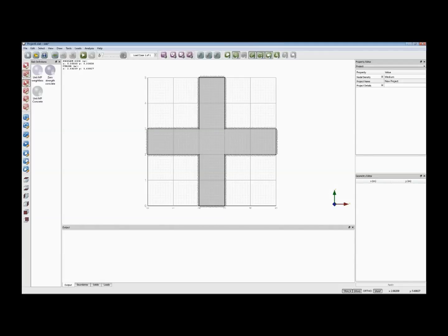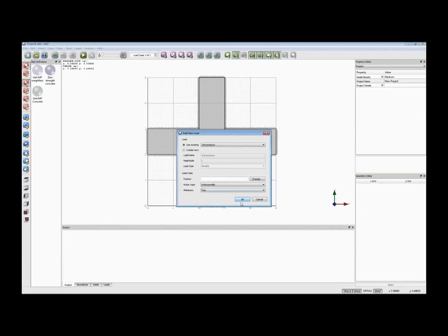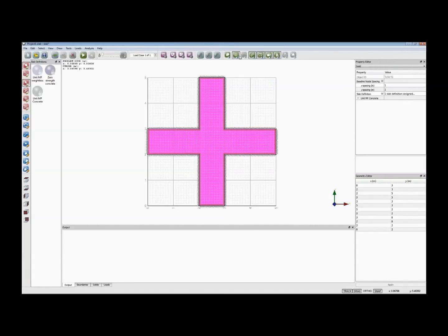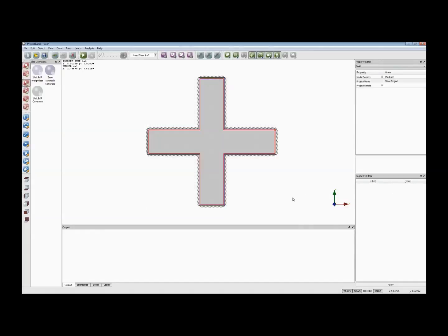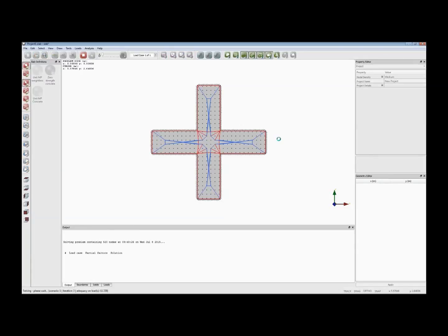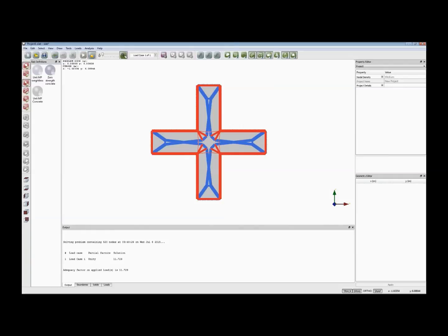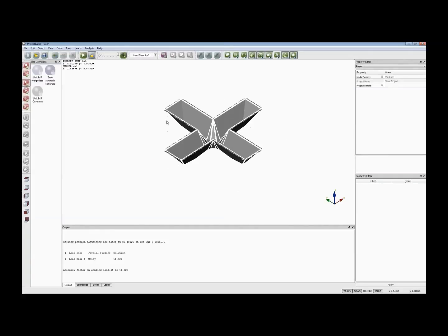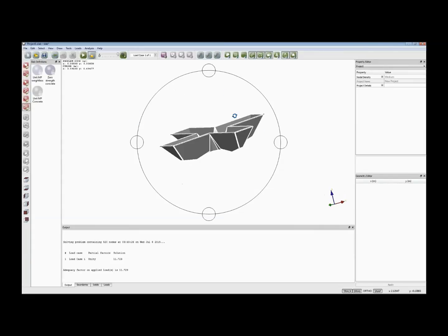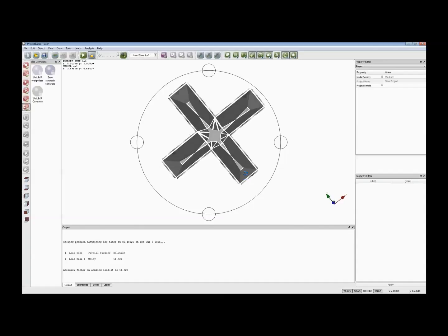So in this case we'll have a pressure load to start with, and we're going to use the existing unit pressure load and apply it to the middle there. So very quickly we've got all the things that we need to be able to solve this problem. We've got a geometry, we've got a material or a slab definition, and we've also got this loading on it. So if I solve now, you can see the type of failure mechanism that occurs there. So we've got sagging right in the center.